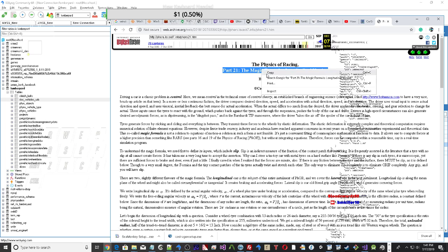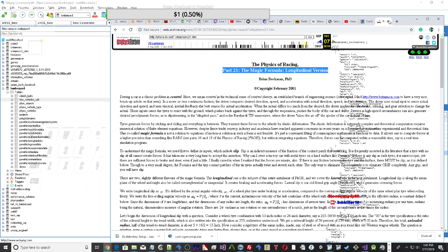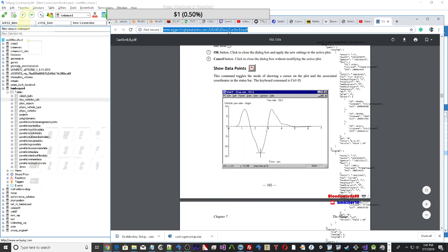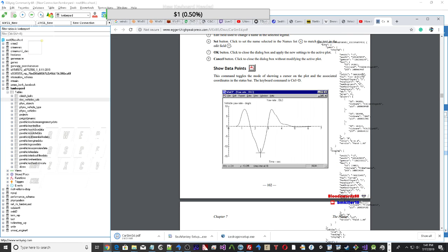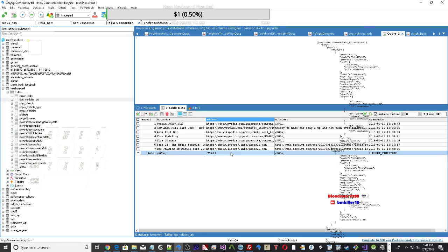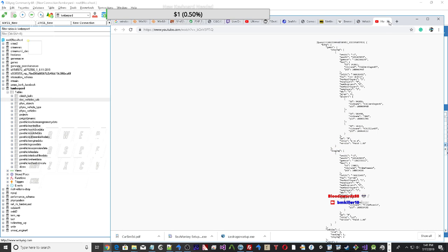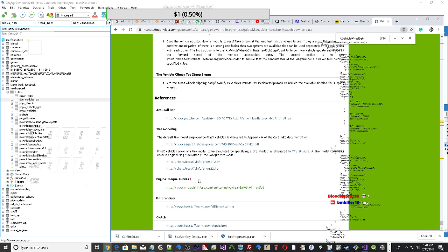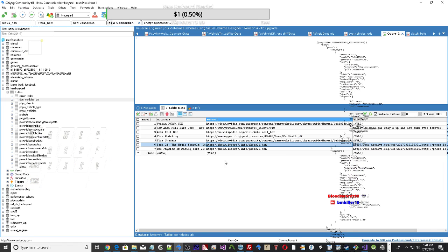Setup drivers data. The following code, taken from snippet Vehicle4W, instantiates a PxVehicleDriveSimData4W, drivers data. //diff PxVehicleDifferential4WData diff; diff.mType = PxVehicleDifferential4WData::eDIFF_TYPE_LS_4WD; driversData.setDiffData(diff);